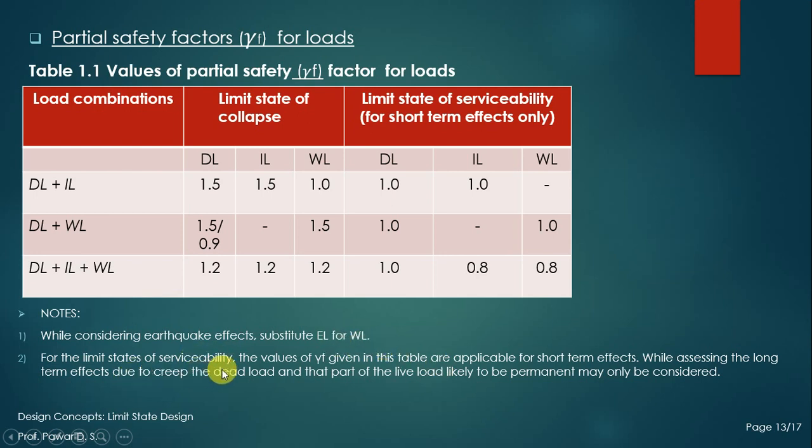For the limit state of serviceability, the values of gamma f given in the table are applicable for the short term effect. While assessing the long term effect due to creep, only the dead load and that part of the live load likely to be permanent may be considered.